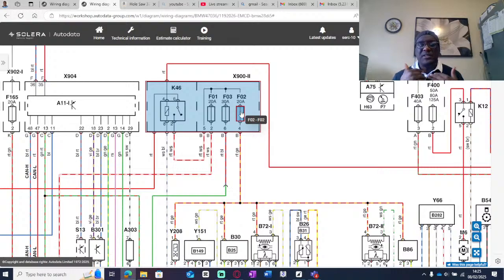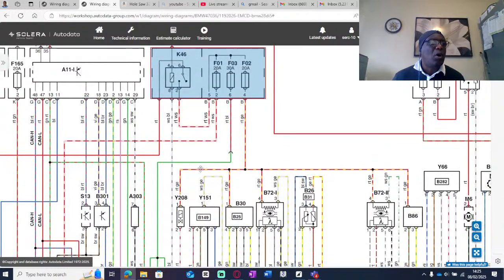So for me as a technician, I'm thinking, hang on here, there's no power here, there's no power there, there's no power there. Something is common here, right? I'm looking for the common component. Here is what is causing that. All these sensors are using one source of power, which is fuse number 2. So straight to fuse number 2, sort fuse number 2. I have sorted all the 5 sensors. Done. So you want to understand these shared circuits. It could be a ground that is shared.